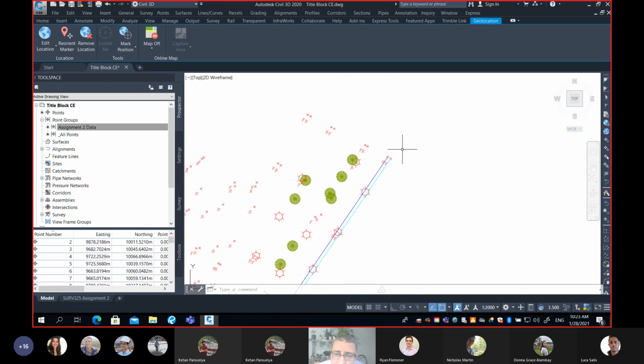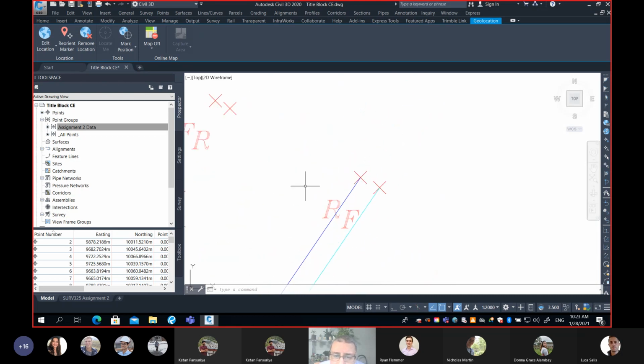My question for you is, should I leave these points together with their description on, or should I hide them? Hide them. And again, I know some of you will ask me, how can I hide them? For sure, there are two ways. You can go and create in your description key set a rule for them, and make the point style and point label style as none.